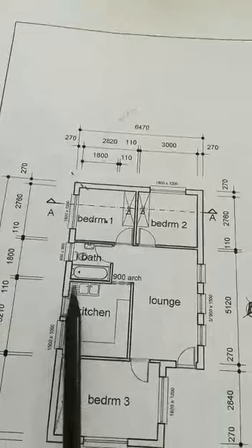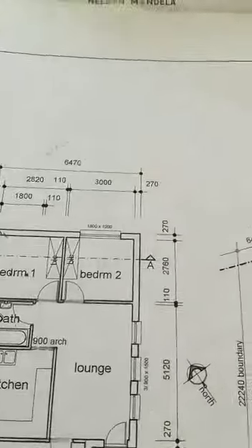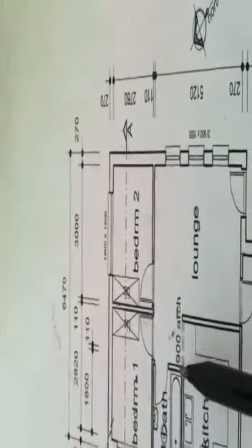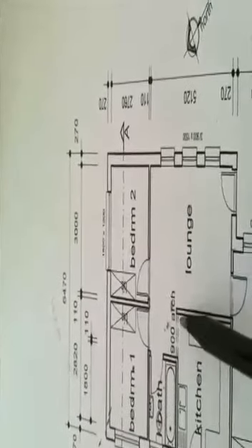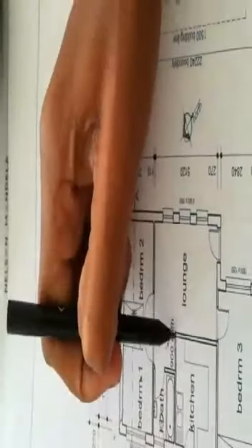Then we have our next horizontal line. Now you can see here, let me just rub this off so you can be able to see. You can see here that you've got these two lines, and that it tells you that over there you've got an arch. So remember, we said all openings, we treat them as if they are not there, we measure through. Which means that horizontal line, we are going to shade that whole horizontal line, and we're going to take its dimension from there up until the end.